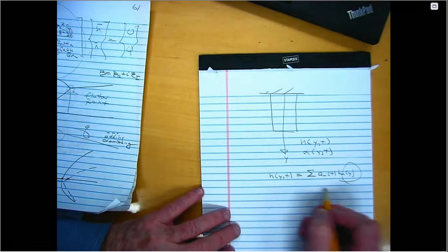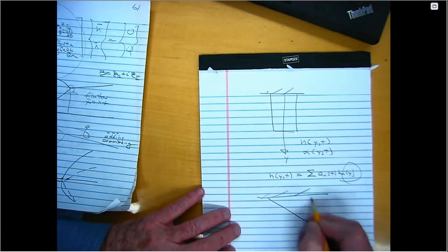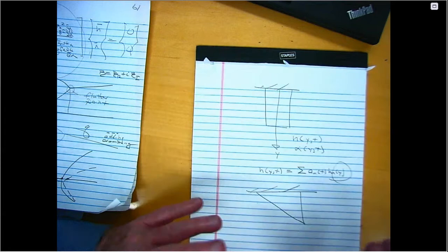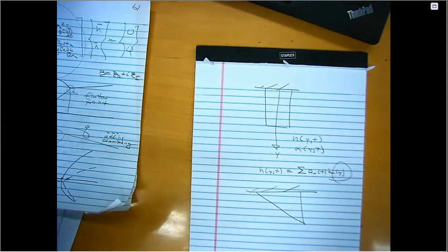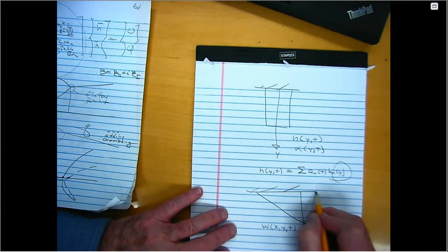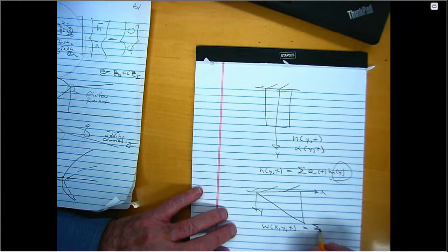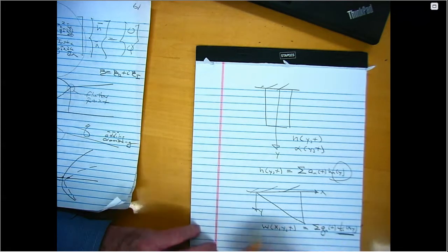And the same thing for alpha, right? In the case of the delta wing, I can't use H and alpha anymore because it's not just bending of the elastic axis and rotation of the axis. Now I've got to use some general deflection W, which depends on X as well as Y and T. So this is the X direction, this is the Y direction. But I can still, I'll call it Q sub n of T, not to be confused with dynamic pressure ever, right? Times some other shapes which depend on X and Y, where again, these are probably the natural modes of this plane.